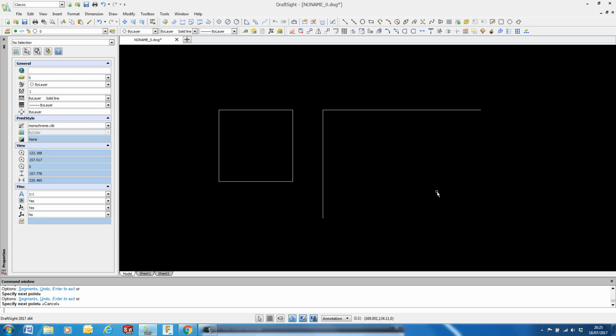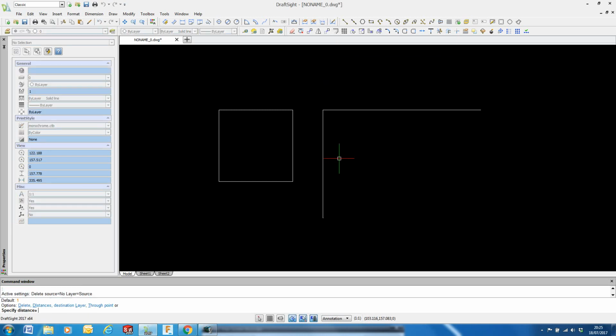One way of drawing particular shapes might be to use the modify toolbar in conjunction with the draw toolbar. So we just produce a line from the draw toolbar, and using the modify toolbar offset, I can construct some new lines. So we're going to use offset and trim as a technique to produce a shape. Really quite useful way of drawing.